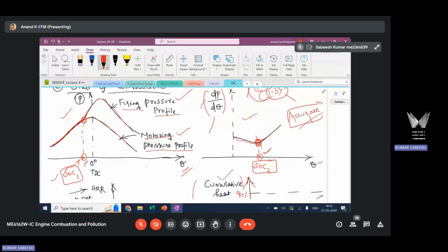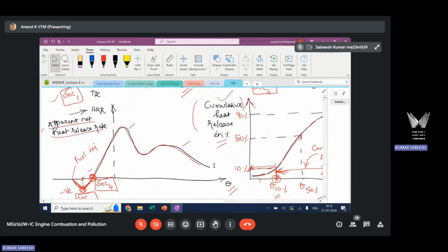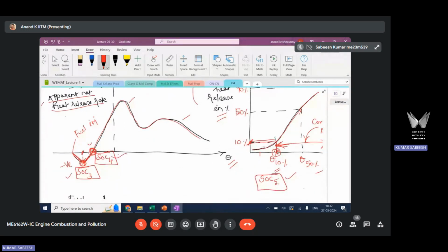We have very high precision equipment to get the pressure information. This is one of the most accurately measured data you have about the combustion phenomena. So you can rely on this because of this. Among these two profiles, criteria 1 and 2, criterion 2 is more reliable because you are resolving more when you take a derivative. That's the reason this is accurate. About the other three criteria, the heat release rate based criteria, the information is inaccurate primarily because you are getting start of combustion from heat release rate, which is a derived parameter from the measured pressure.